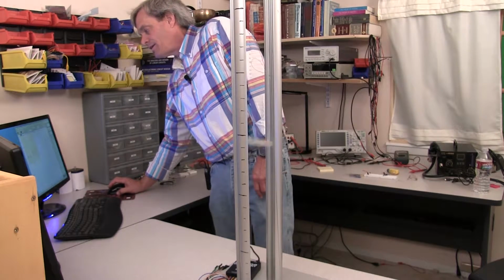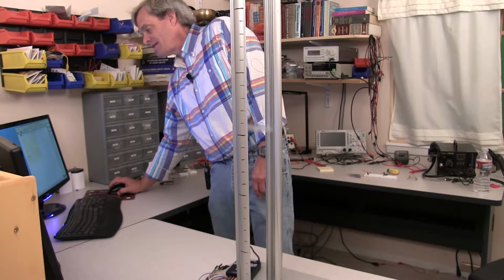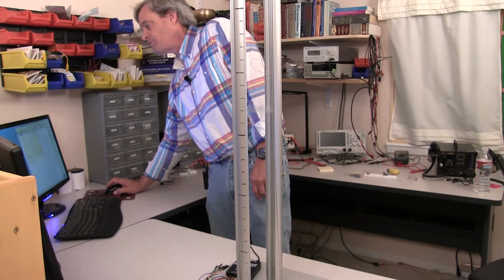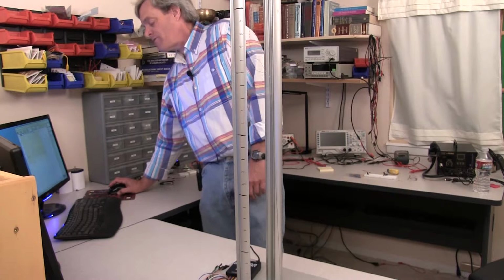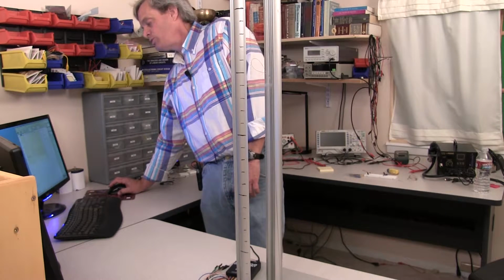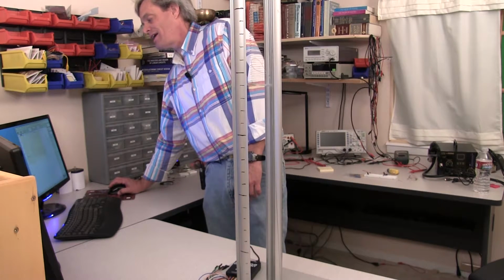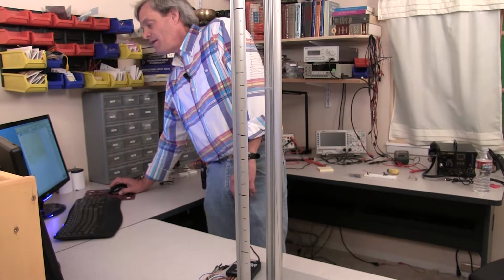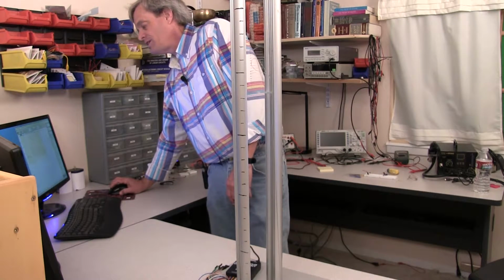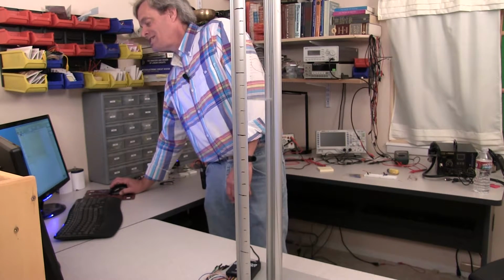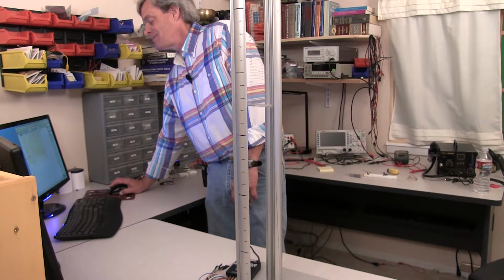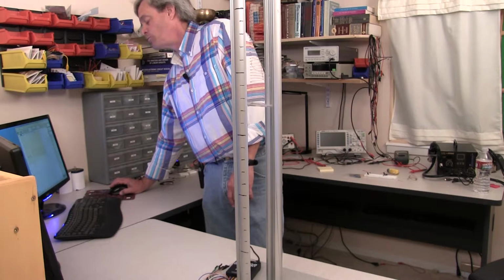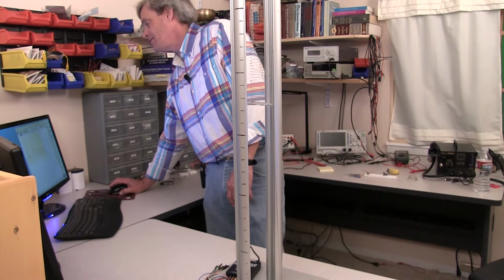The yellow line on the scope is the output from the sensor. The blue line is the output from the filter. The vertical scales on these two lines differ by a factor of 10, so the blue line voltage is 10 times that of the yellow line. That means that over my full scale of displacement, I'm getting almost 2 volts difference. If the displacement is about 15 inches, that means that I'm getting something more than 1/10 of a volt per inch, which is a pretty good sensitivity.